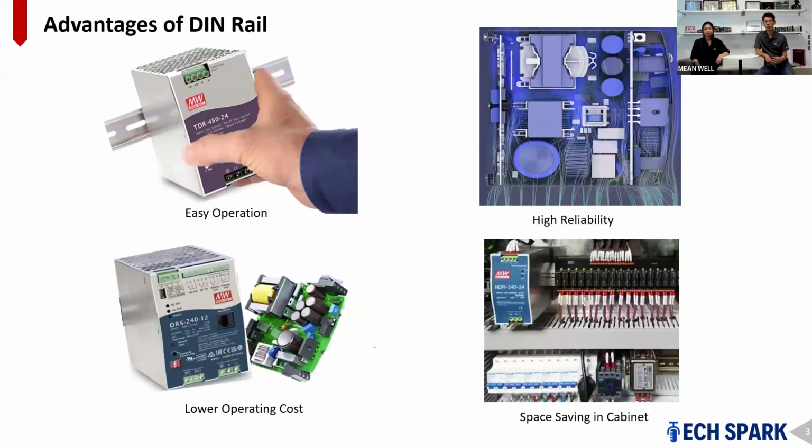Yeah. First of all, it provides easy operation for the users. Installing DIN rail power supplies is easy and can be carried out quickly. The device is simply attached to the DIN rail and is then wired to the AC mains and the load. Connection options such as push-in terminals allow the power supply to be installed easily. The DIN rail power supply is then immediately ready for operation.